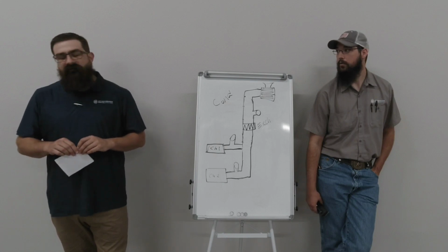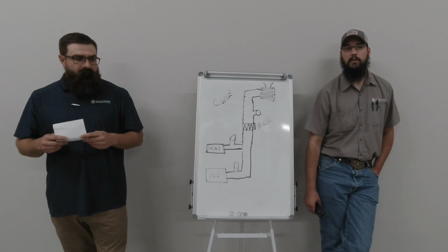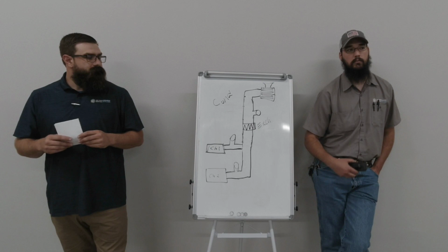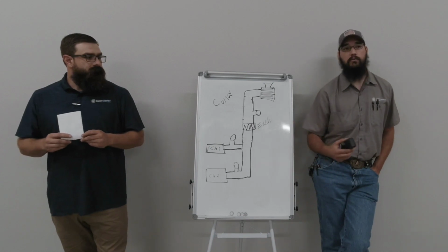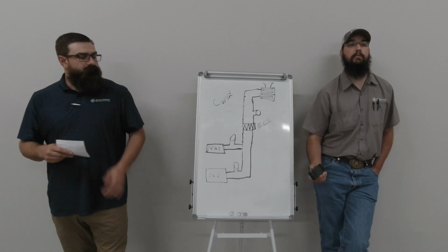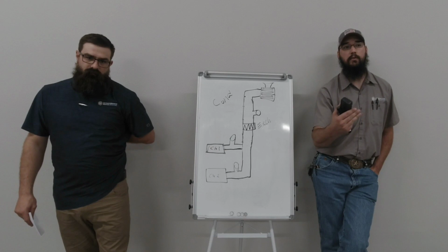Too much flow. Yeah, so it's a really high flow, too much volume, which does have its own set of issues. It'll have a very low differential pressure. So the lower the differential, the more flow you have. The higher the differential, the less flow you have, because you have less force behind the water pushing it through there.